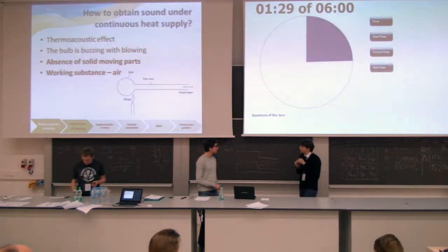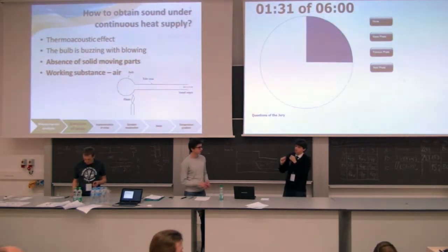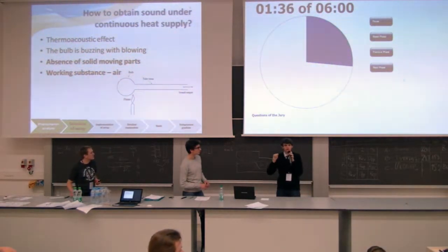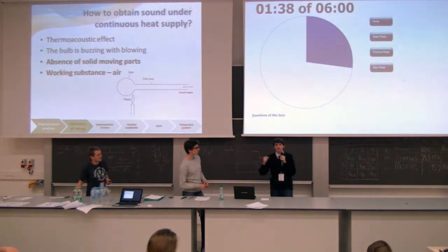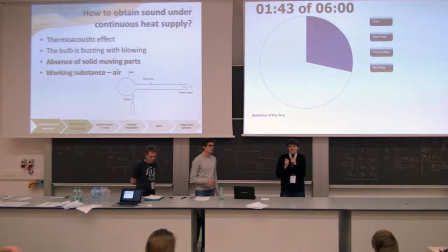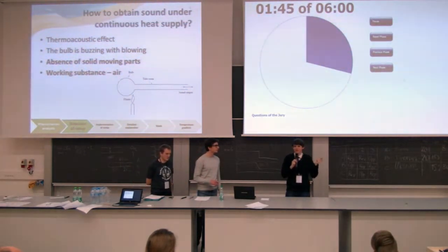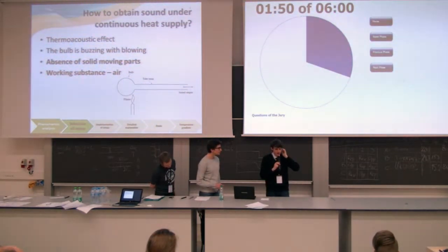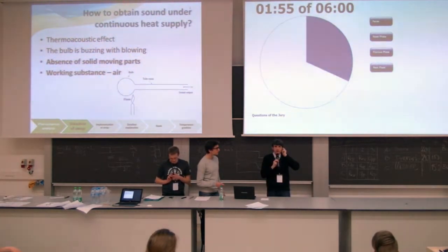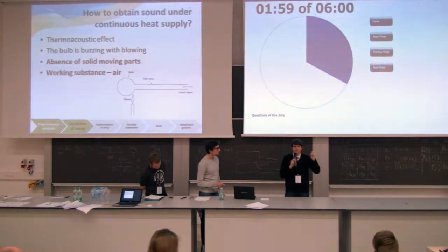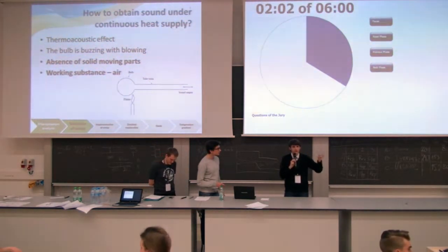The stack has two main roles: to create and maintain the temperature gradient, and to heat and cool the air. I have never heard any mention of the Joule-Thomson effect in articles. I think we can take it into account if we had a very little core size, even more.